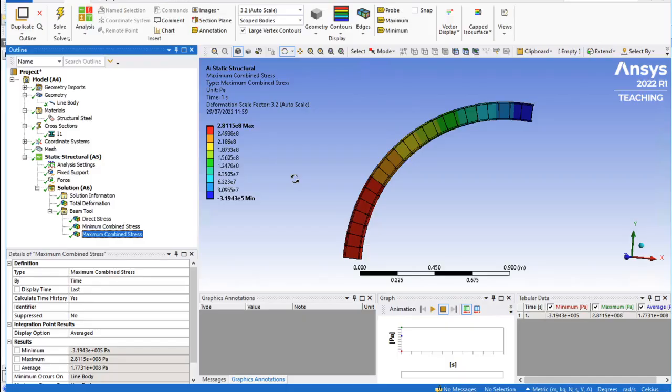You will see later in the slides that we are discussing the effects of inadequate support. For instance, you can free the rotations here and see what happens. Essentially the software cannot succeed. And that is what we call the singular stiffness matrix, which we should be aware of, and we should always make sure that we are avoiding it. That is one of the common problems that happens when we are doing FEA simulations.